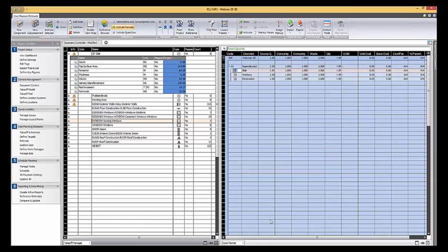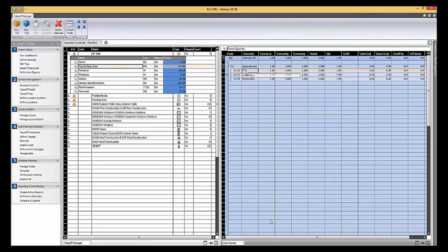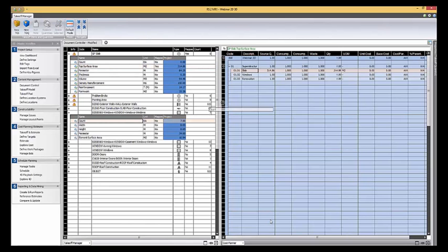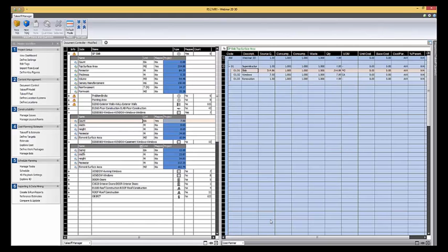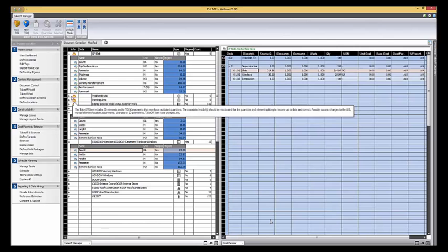And I'm just going to add some code to that as well. And then all I have to do now is drag and drop those quantities into my cost plan. So that 314 meters squared for the slab, those 7 windows, and actually I'm going to add these other 13 windows here as well, because you can combine multiple takeoffs into one bit of the cost plan. And then I'll take that pointing area as well.